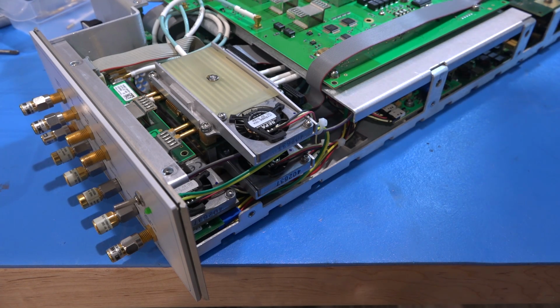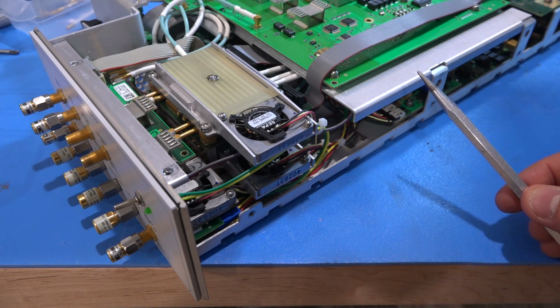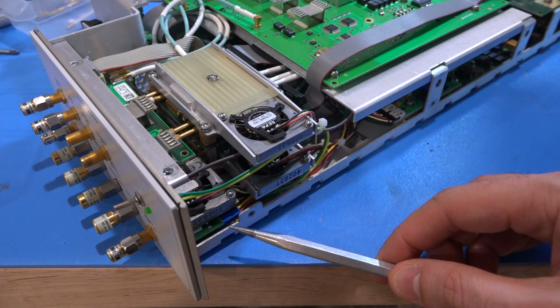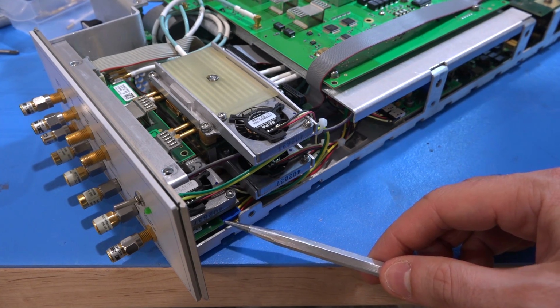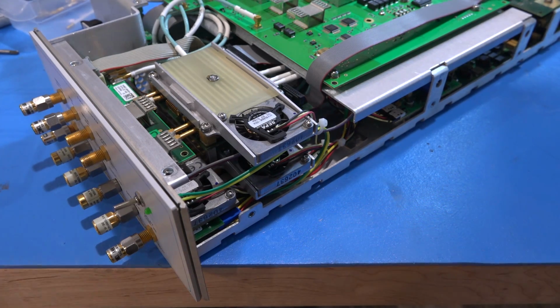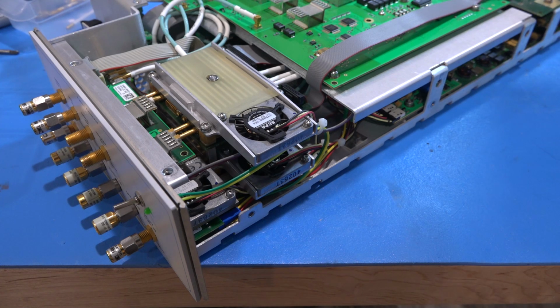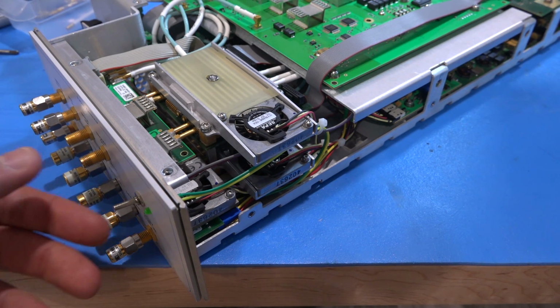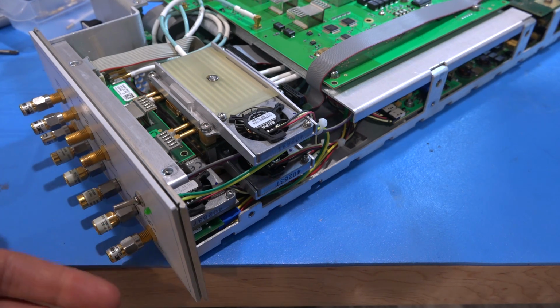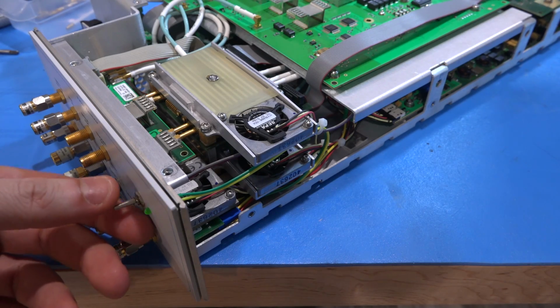Instead, I came up with a different solution. The main issue is that when this thing triggers that it thinks there's an overload condition, when there isn't, it disconnects the front end relay, that little board that I showed you, and therefore there is no way to drive that port anymore. So I built into it an override switch with a little LED here that shows you whether you're overriding the internal signal and enabling the port regardless of what the software thinks is going on. This way we should be able to at least see if this port is working and be able to introduce jitter into the eye diagram manually by using this switch.